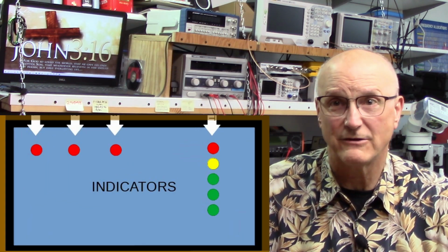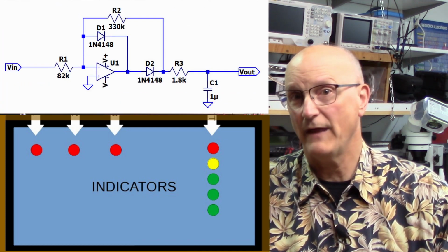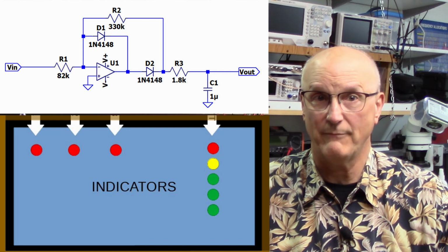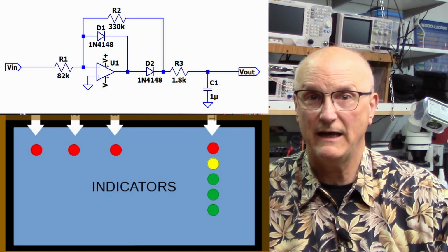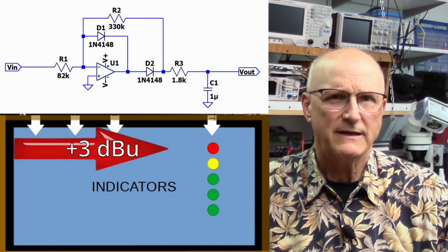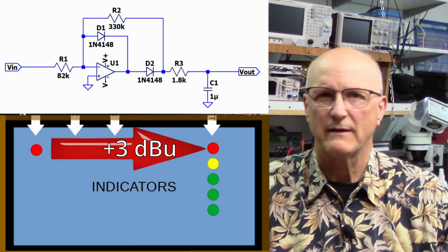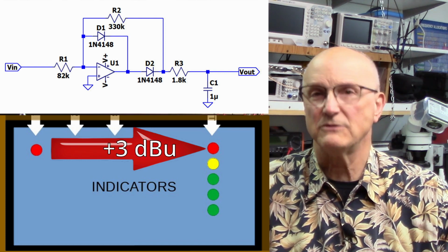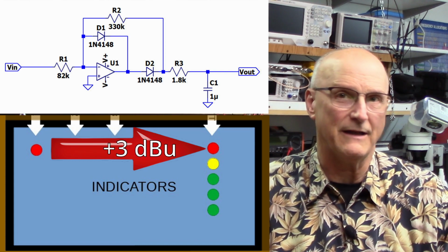But we can't stop here because we have the indicators function block, which also uses op amps to run the output level meter averaging amplifier. Now the averaging amplifier has gain to it that we need for the comparators. The highest level LED is plus 3 dBu, but we need to be absolutely linear to this point for the meter to actually mean anything.